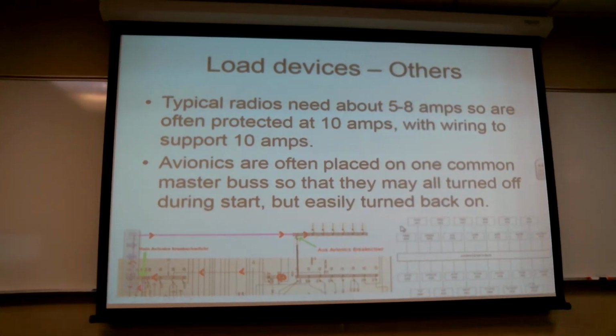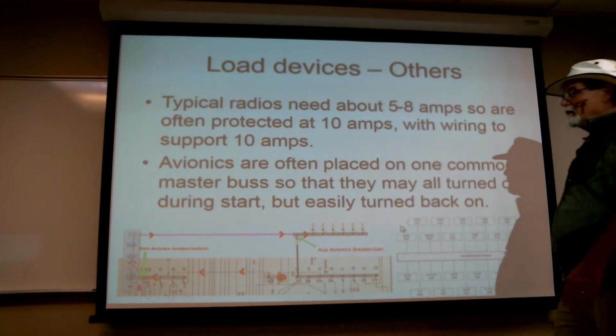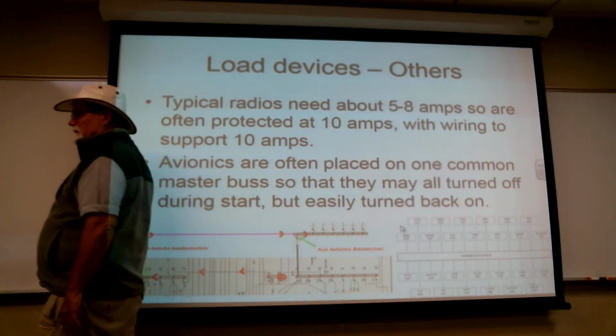And then, of course, oftentimes you'll see them say, all right, run off one circuit breaker with these 2 wires over to the unit. And that can be a little confusing because it depends on the unit. If it's a combined unit, like for example, the Garmin 430s and 530s, they have 2 power leads for the radio, 2 ground leads, 2 power leads for the nav side, as well as additional power leads for other elements within the unit, as well as some power outs coming off of the unit.